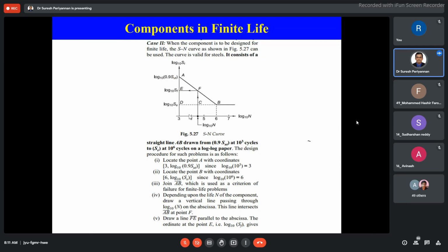For example, the crankshaft material goes through fatigue testing, and we might have studied the endurance limit strength of the crankshaft material in laboratory testing. In practical applications, we have a standard SN curve based on laboratory tests. We have a standard SN curve for the crankshaft material.